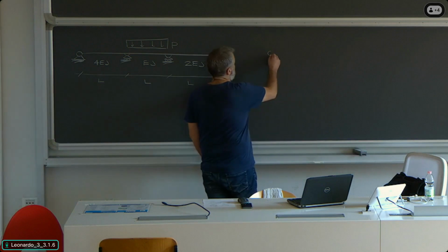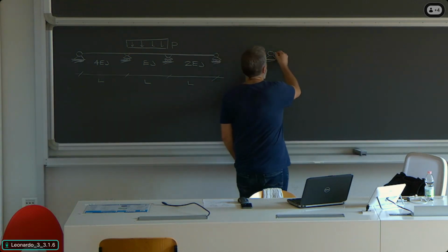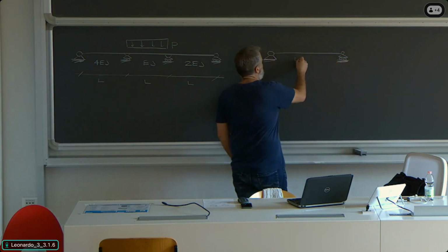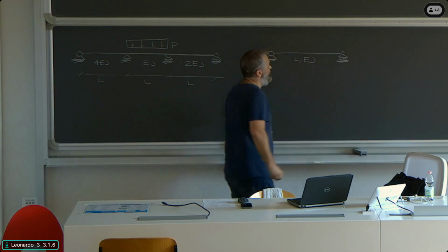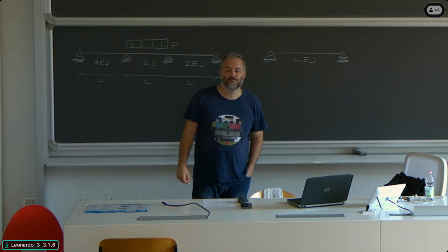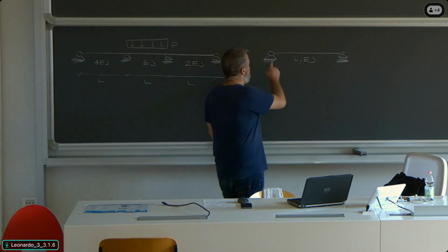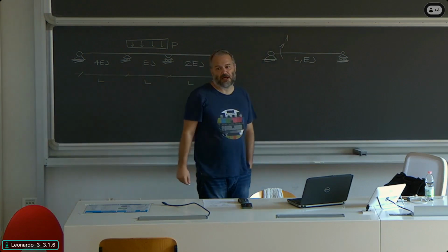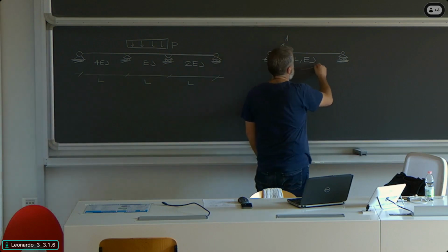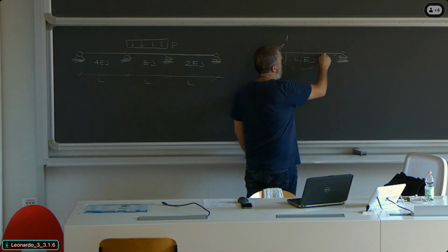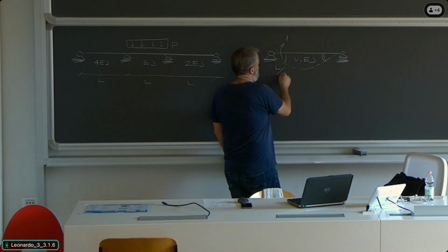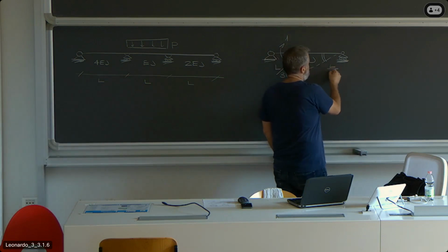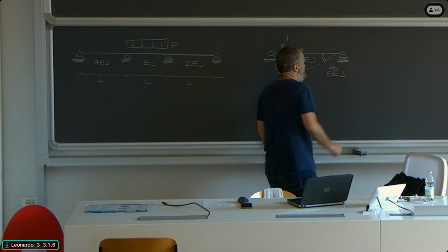One is this. Standard beam, which means a beam with length L and bending stiffness EJ, simply supported, so hinge and roller, with a moment of unit value applied at one end. Under these conditions, the two rotations are given. The rotation at the first end is L divided by 3EJ, and the rotation at the second end is L divided by 6EJ.